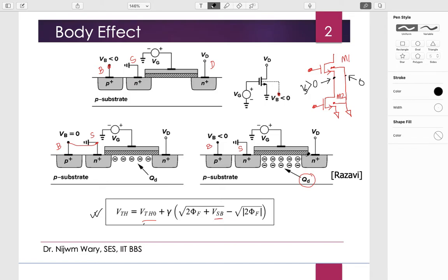Inversion layer is formed, so that the channel is formed, right? Basically it is sufficient to flow the current. Sir, in this case, if we don't look at the equation and just see figure 1 that you showed, when V bulk is 0, there was just one layer of electrons, one layer of negative charge, without changing anything in the VGS.